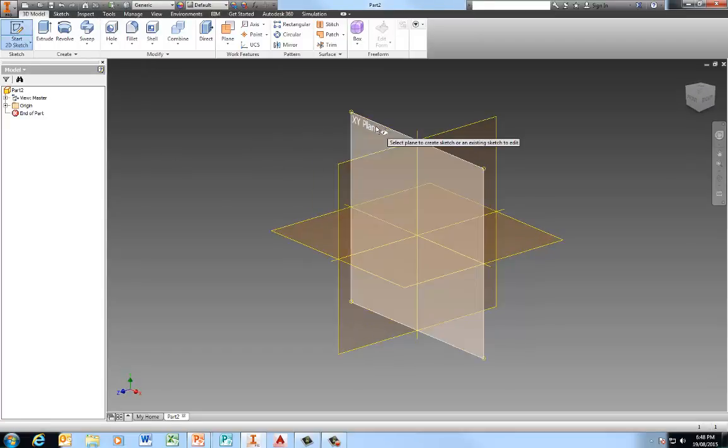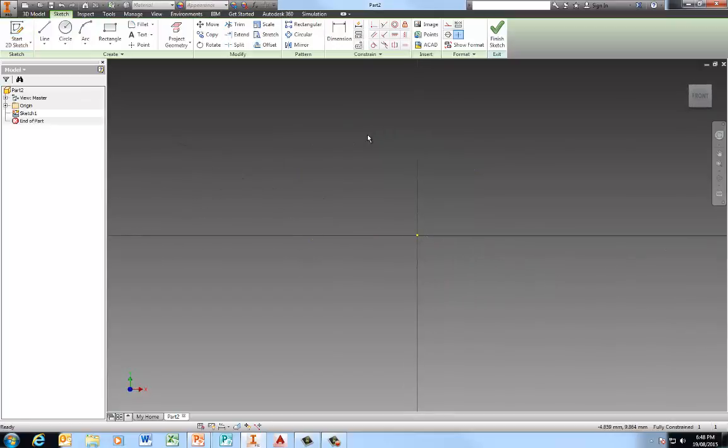We'll start a 2D sketch on one of the origin planes, and now we need to look at the Demo 11 exercise sheet and observe that in the front view the object is symmetrical and located around a central axis. So what we will be doing here is drawing a profile that represents either the left hand or right hand side of that front view, with a line that will actually pass down the center of the object, being the axis about which we will revolve our final profile.